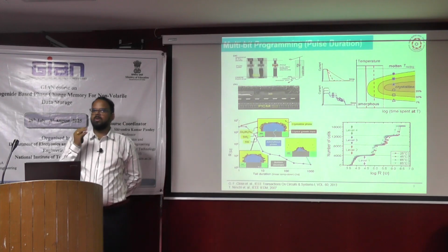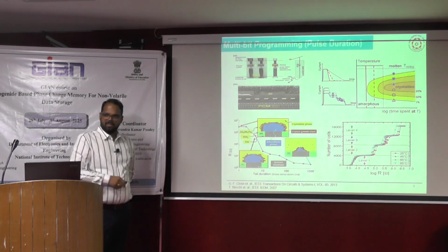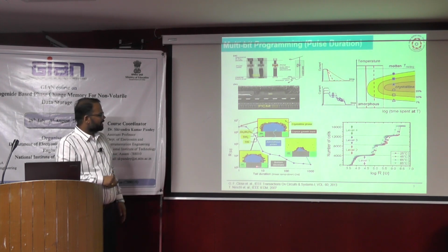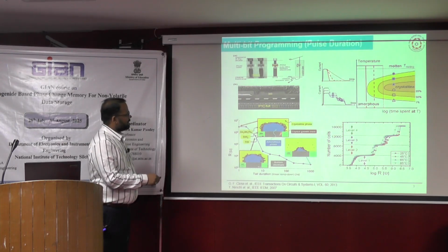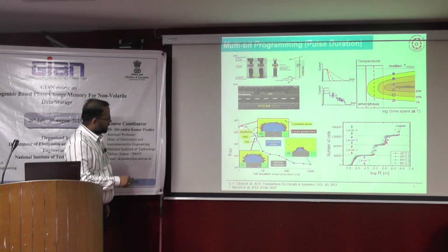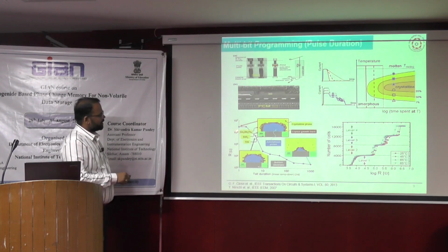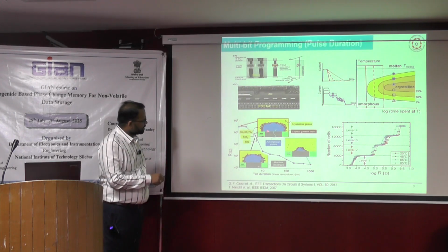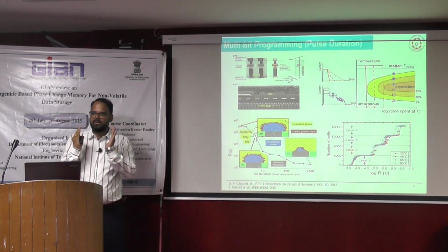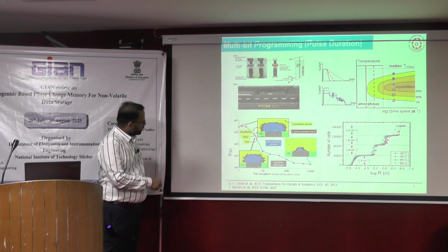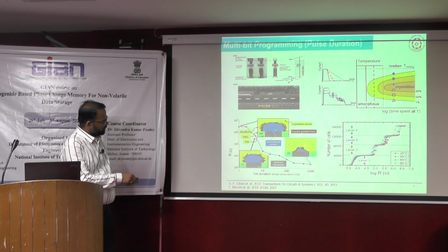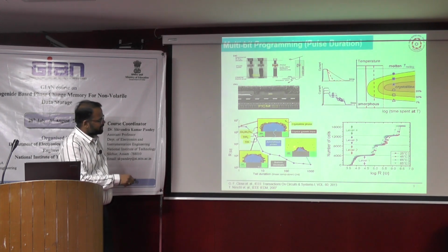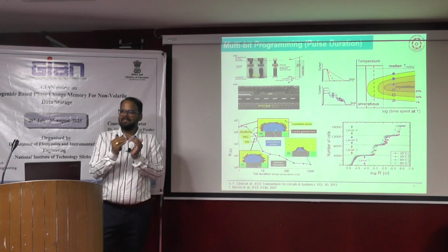If you have control over the tail duration, you can easily identify the volume inside the phase change material. As you can see, initially when this duration is less, the material shows high resistance, and more of this region is visible. As you move toward the higher side of the tail duration, it gets crystallized and this region shrinks.